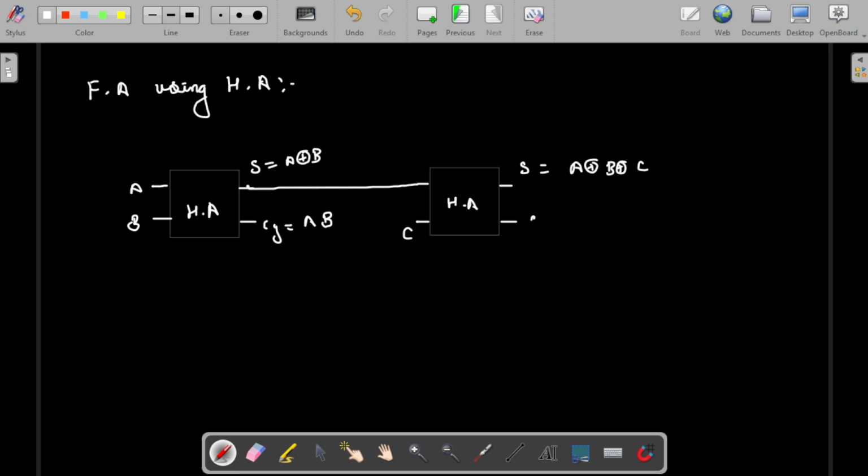So here the carry needs to be AB plus BC plus CA, or the other term, with XOR, (A XOR B)C plus AB. So both things we need. So we know that this one can do the multiplication of this one. So I'm just erasing to represent that one.